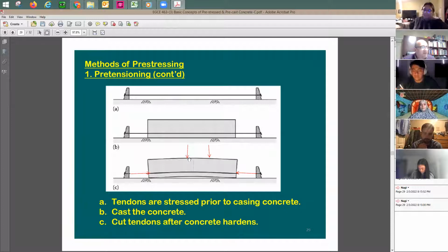This means they're going to be counteracting the effect of this pre-stressing. In other words, this pre-stressing that you're doing here, the compression that you put on the bottom of the concrete beam, is counteracting the effect of this loading. Because look what happened. When I was talking about design of conventional reinforced concrete, I said concrete is going to be failing once the strain is approaching 0.003 on the top as compression. Before you start the loading, I put some tension there.